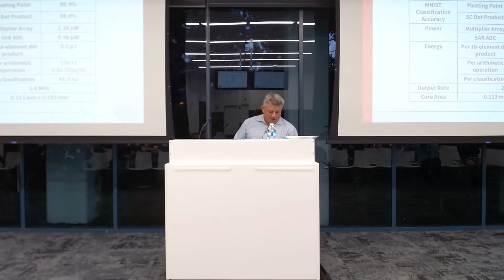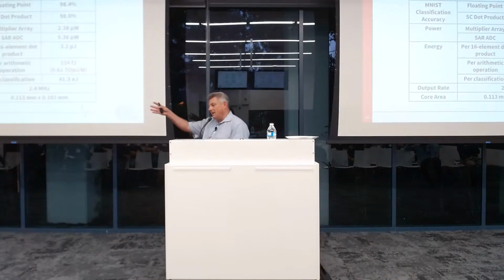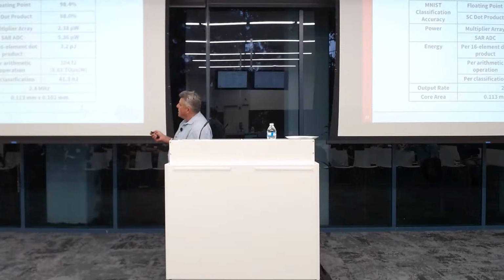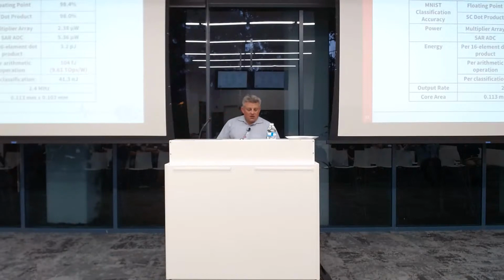And so how well did we do? Not so great. So this thing came out, and at the end of the day, built, measured everything, right? No, not simulation. No, really built, measured in the lab. And so it's about 104 femtojoules per operation. So this is sort of the multiply adds averaged out. And so, I'm also just barely scratching the 10 TOPS per watt with this thing. So this was not super successful.